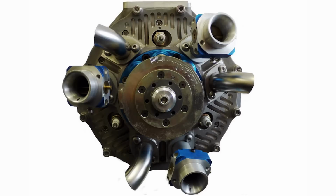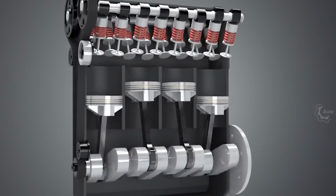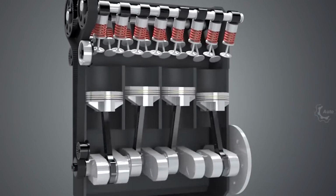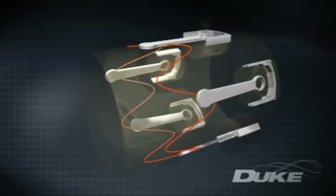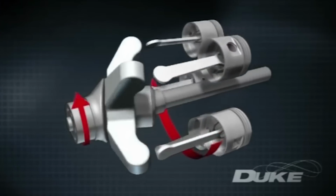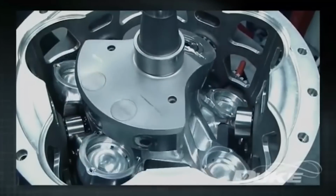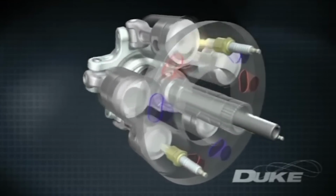Now to a coaxial motor. A coaxial motor still uses explosions to move the pistons up and down, but where a traditional internal combustion engine turns the linear motion of the piston into rotational force by using a movable conrod, the coaxial engine doesn't. The coaxial motor keeps all the linear force. The pistons are placed around in a circle, and they just move straight up and down within their own cylinder. The cylinder groups rotate slowly next to a monoplane ported surface. This ported surface houses the air, fuel, and spark chambers.